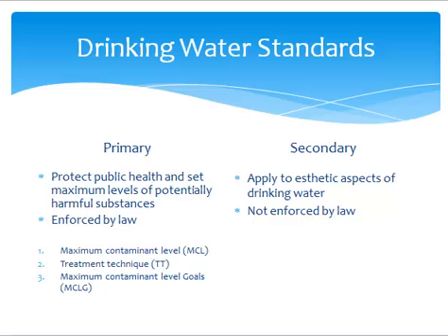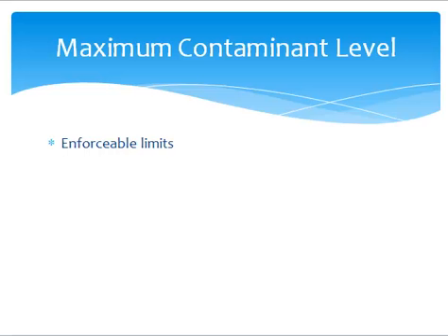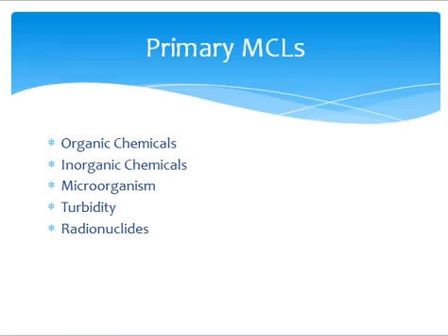It is important to know the detention time. To calculate the theoretical time water needs to be in a settling tank to allow sedimentation to occur, we use the formula where V is equal to the volume of water in the tank, and Q is the average flow rate.